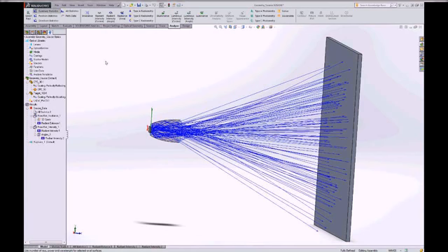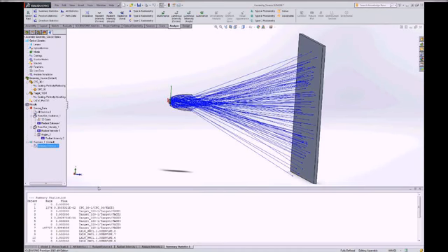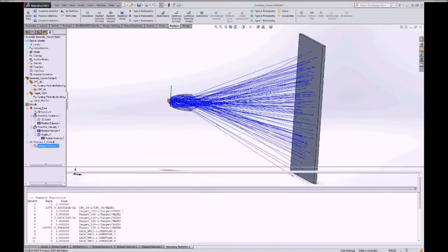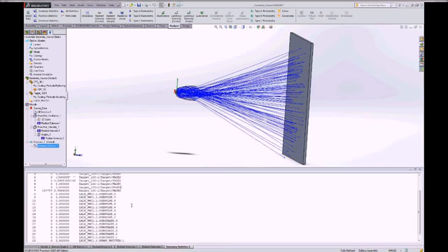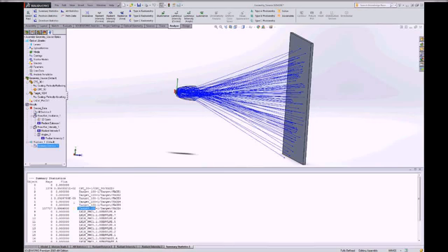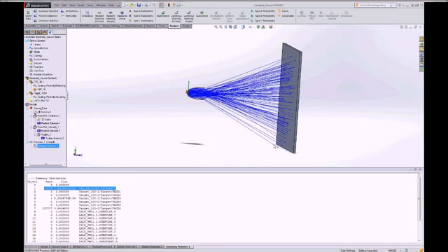And what I'm going to do is just look at the summary statistics. If we look at the summary statistics here, we can see that our rays are either on the target or the last, you'll notice they say they're on the CPC. What that means is the last object they interacted with was the CPC. And you notice we only saw one of them, but we only see about 1% of the rays drawn, so that's effectively what we would expect. We wouldn't have expected to see more than 1 or 2 of those rays because statistically that wouldn't have happened.